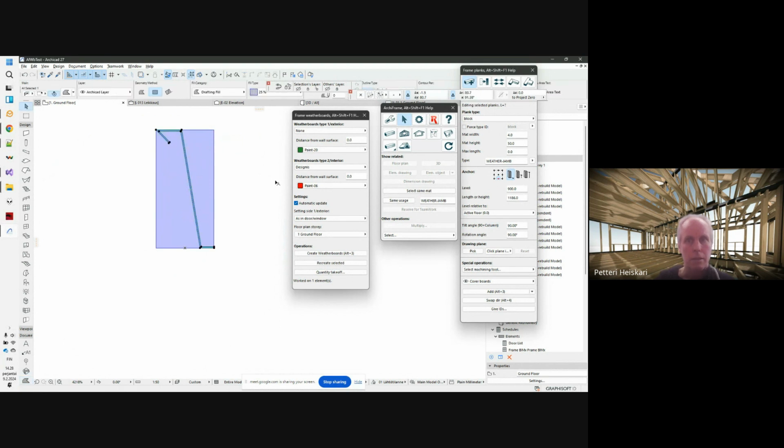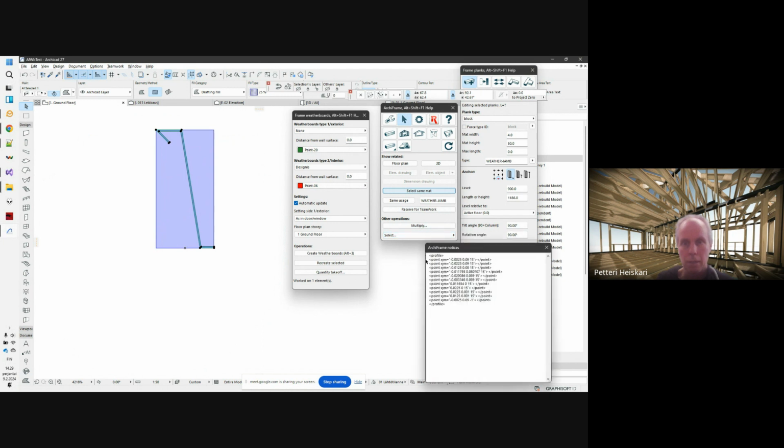And to use the profile, I need to select the fill, which is orientated this way. So this is the width of the plank, and this is the height direction on y-axis. And then in this arrow tool, there is dump profile from fill that will dump the needed XML that I copy paste to my raw material list.